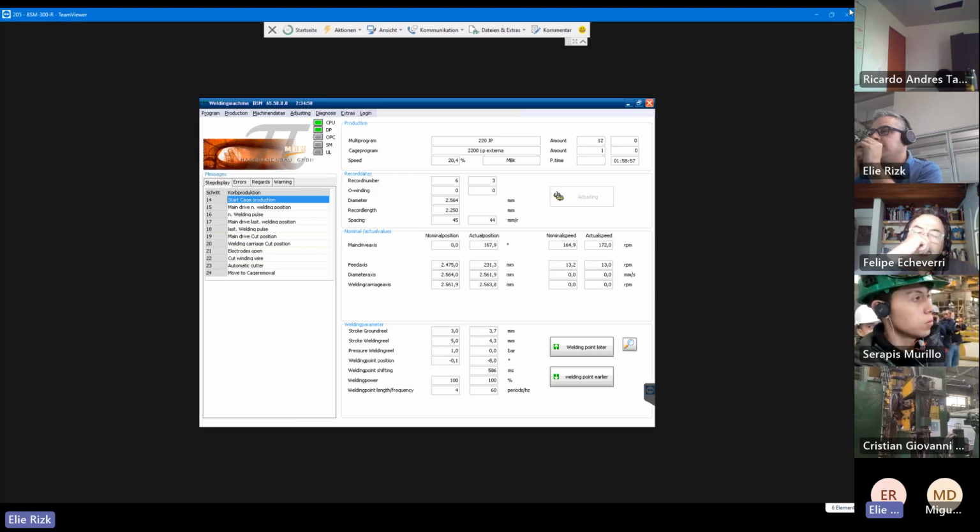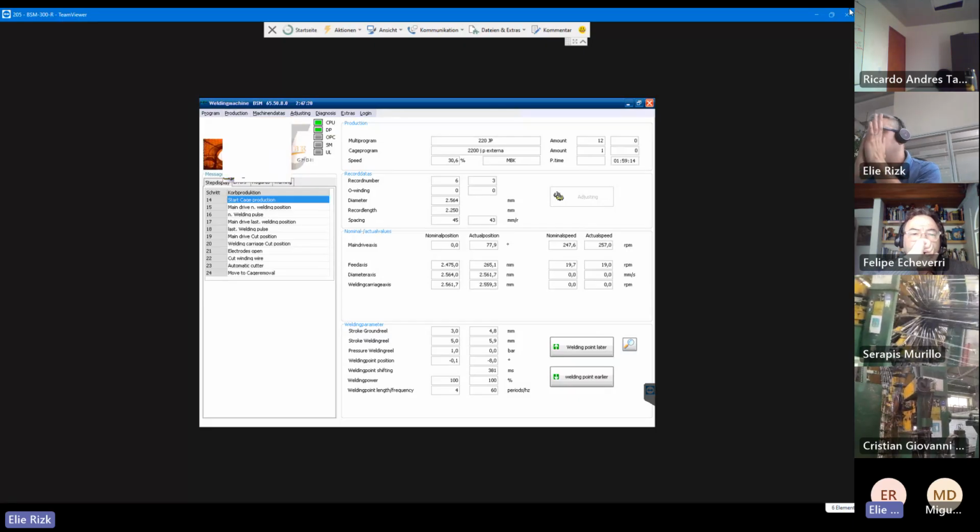Because you can regulate this. There is a pressure regulator. I think for the clamping bar, you have to set it to 4 bar, and you can check this. And the operator should always push the bar to the end until it is touching the clamping.